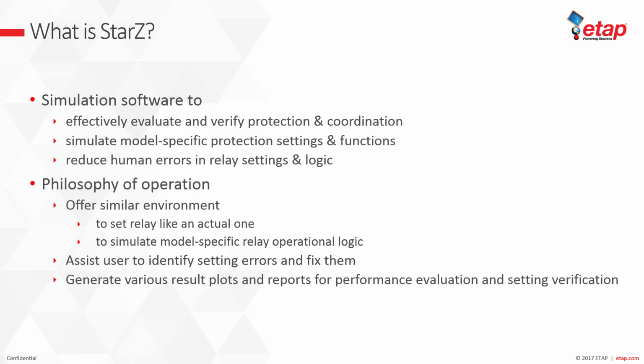For those that are new to ETAP, STAR is the software module that is used widely in industry for overcurrent protection coordination for many years. So StarZ is its new sibling, which inherits STAR functionality to evaluate overcurrent protection devices, while it also supports impedance protection. So Z stands for impedance protection. That's additional functionality to STAR that is incorporated as part of the StarZ module.